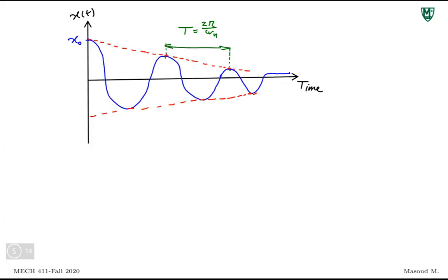Now that line's slope would be, let me try harder, if you look at this line's slope, that would be minus 2 mu N omega n over pi k. Omega n is the natural frequency, N being the normal force, which you can replace with mg, depending on what kind of system you have. That's the slope that this line makes with the horizontal line.